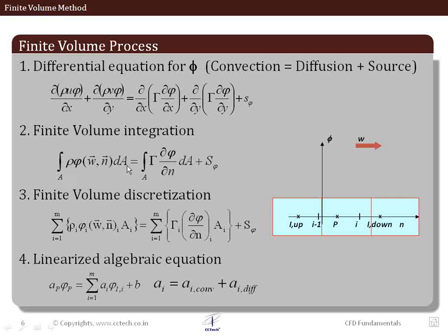And these surface integrals, our overall integral equation, when it is applied over finite volumes, so discrete geometry, in that case we obtain a discrete form of the equations. So you can see integration, which is a continuous representation, is converted into a discrete representation, that is summation form. As we saw in the finite difference method, we converted d by dx or dou by dou x, if it's a partial differential equation, into a difference equation. In the finite volume method, what we are doing is we are converting these integrals into summations, and that's the discretization.